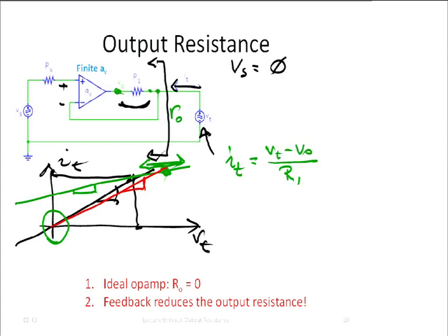So then we need a second equation for V out. Now the amplifier here has a finite gain. So now I said that this is 0, so this is 0, then also this is 0, right? Because Vs is equal to 0, and no current flows into the positive terminal of the operational amplifier. Consequently, there is no voltage drop across RS.